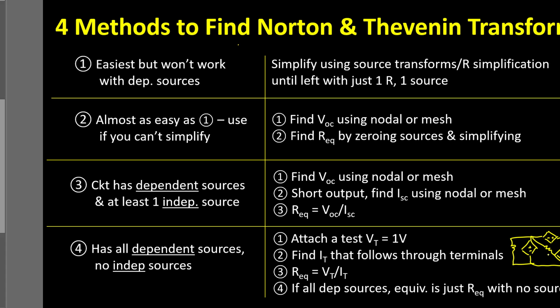So the Thevenin equivalent of that complex thing will always look like a single resistor. The only question is, what will that resistor be? The way you determine it is to attach a test 1 volt source to the output. Determine the current that flows into your circuit, call it I test, since we've applied a V test of 1 volt.